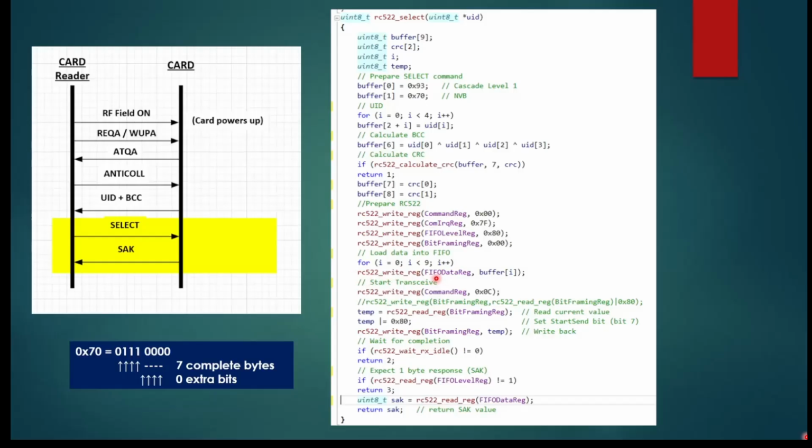So we go ahead and write to the FIFO, and we send message by message, which is going to be our 8 parameters. At this point, I'm filling up the buffer. Now we have to send the command so the select gets sent. So we send our hex 0C.